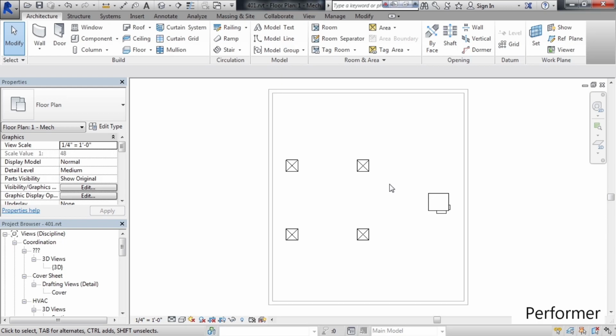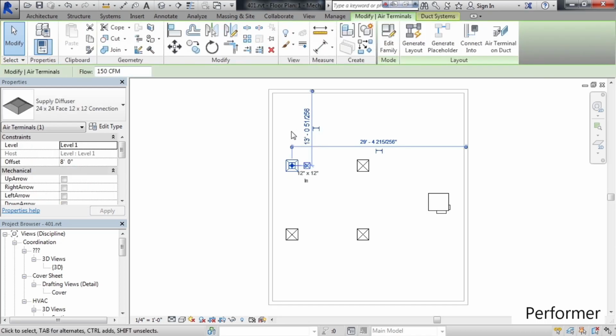Now, let's drag another window to select the other way. So again, in the middle of the actual diffusers, hold the left mouse button down, start to move your mouse to the left. And what you'll notice is this window is dashed. So this is what's called a crossing window, meaning it will select whatever it crosses or whatever it surrounds. So as you can see, as soon as it crosses over that diffuser, it selects it. And as soon as you release the mouse button, it will select that actual diffuser.